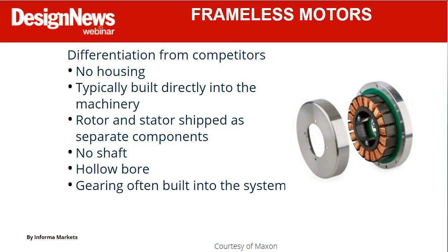And again, if you're looking at an exoskeleton, if you're looking at some kind of a robotic solution, suddenly you've got much smaller form factors. You can use a gear, but you can also do direct drive so that you don't have any kind of backlash.